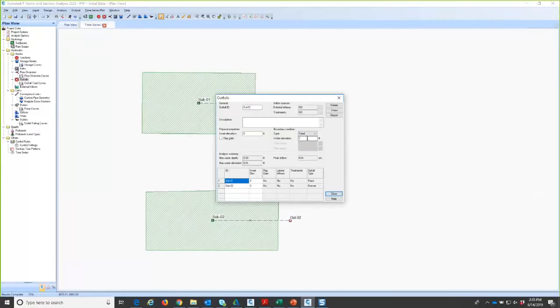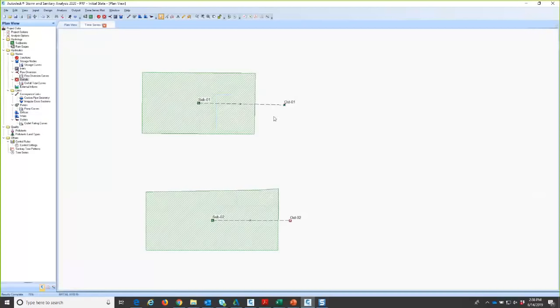Say I had a fixed water elevation of 400 at the outfall, and the inverts were all at, let's say, 390. So my water surface elevation is above my outlet. What is that going to do to my system? I could run this scenario, save the results, then make a new file, change my boundary condition, and rerun the results. Flipping back and forth between different files to get the output so you could compare them could become laborious.